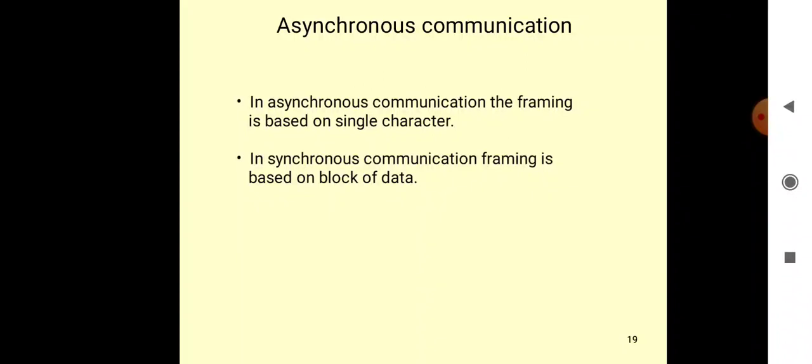What is the need for start and stop bits? In asynchronous transmission, we send one character with start and stop bits. The purpose of start and stop bits in an asynchronous system is to identify the beginning and ending of each character by the receiver. The start bit is transmitted at the beginning of each character, and at least one stop bit is sent at the end of the character.